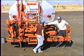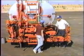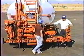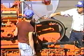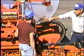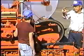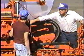Very first thing it gets to right here is a swivel joint, and that swivel joint has to swivel. That is, I can move the hose up and down here, and that's so that when the bar goes up and down or sideways, it doesn't put a tremendous strain on this hose. Very simple swivel joint. If it drips, loosen the set screw on it and snug up the pin nut.